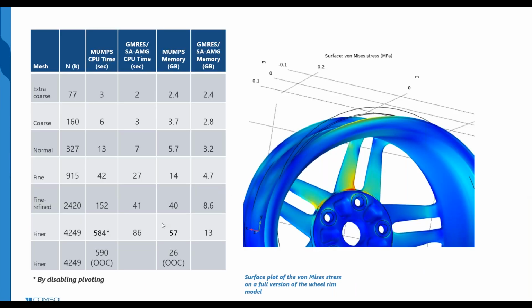So here is a table where I've used a modern state-of-the-art iterative solver with preconditioning. Compare that to MUMPS. I know MUMPS can be beaten by PARDISO, but in this case, I just wanted to show the behavior. It's not dramatically different with PARDISO.